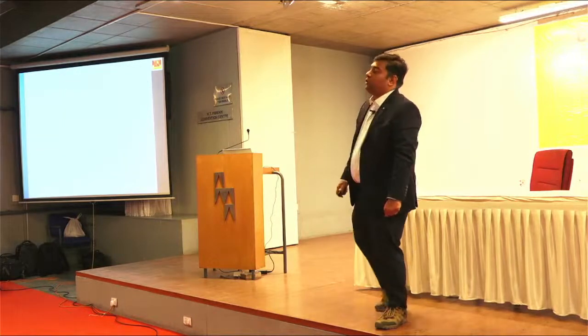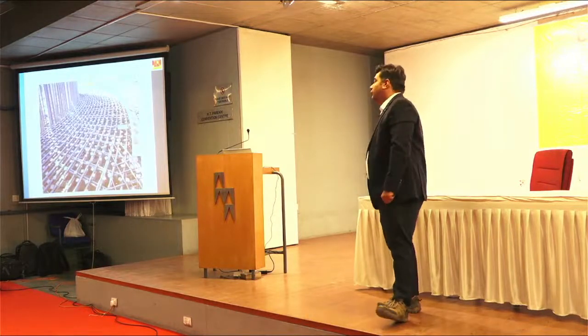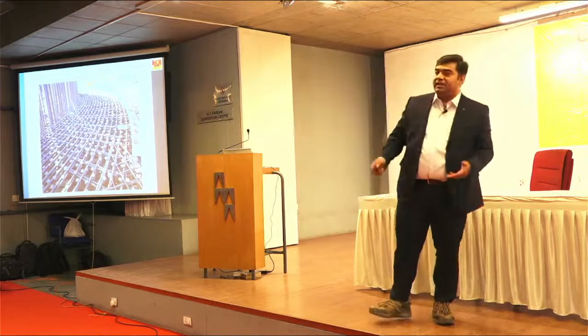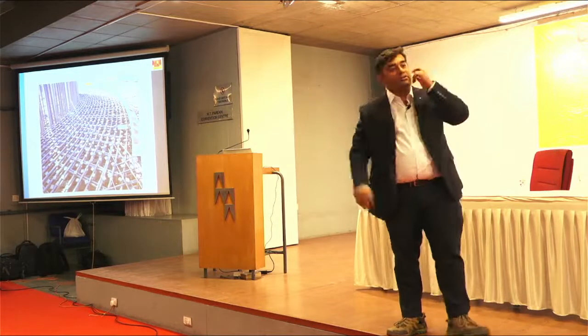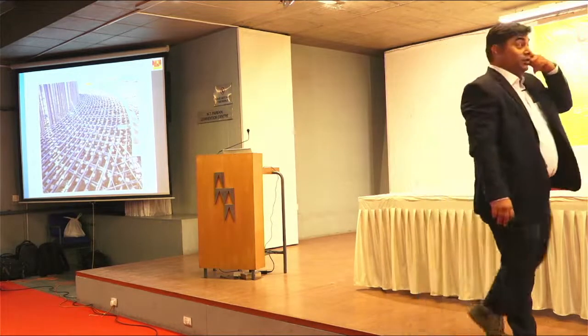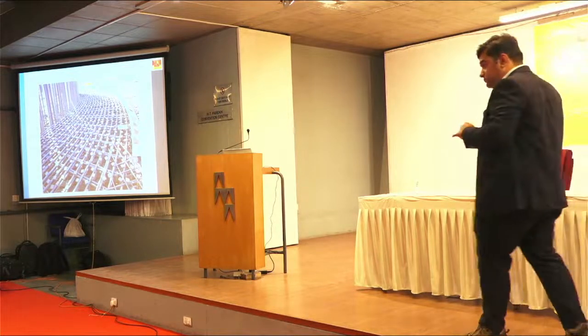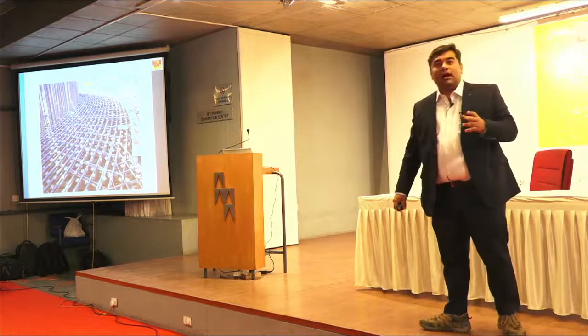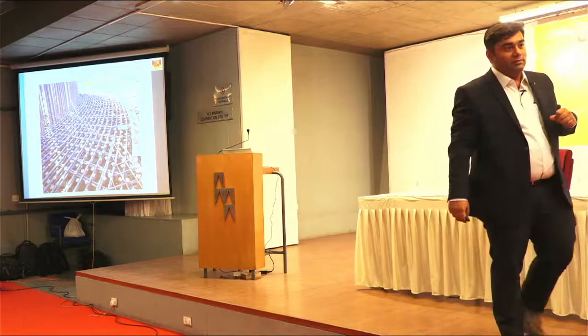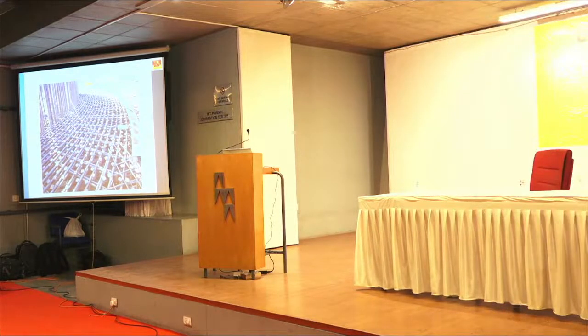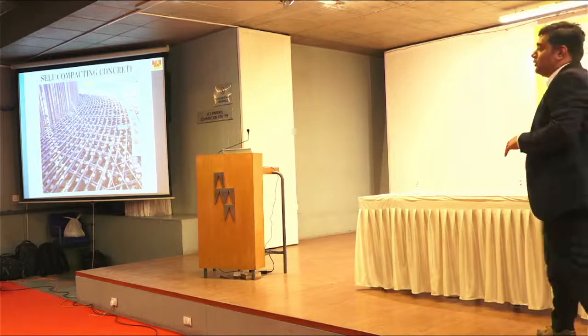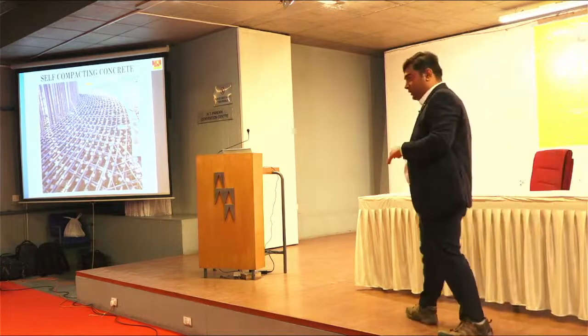Okay, so this was stamped concrete. Moving on. As civil engineers, we will face this kind of structure at site. If you place concrete, how will you compact the concrete you have placed? Vibrator? I don't think the vibrator will go inside. Self-compacting concrete. Okay, so you all know about it. So this will be concreted with self-compacting concrete.